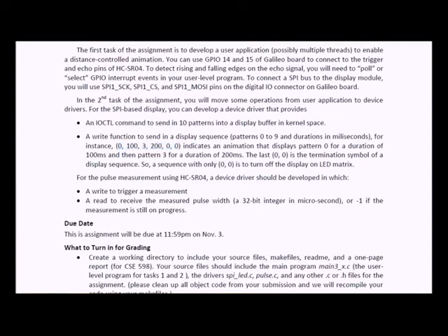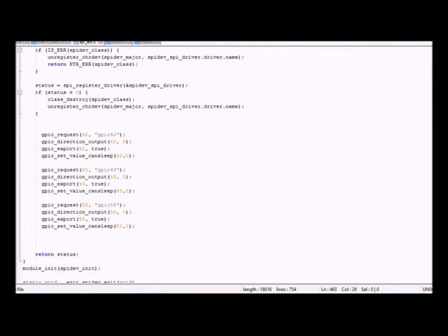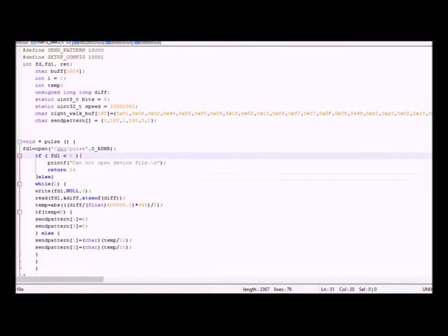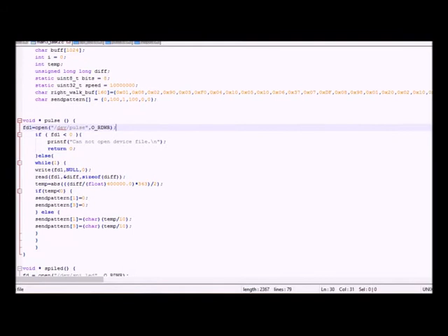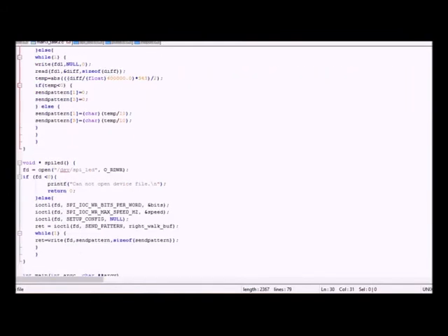Now let us look into the various drivers and the user application that we developed to use those drivers to work with the LED matrix as well as the ultrasonic sensor. If we look into the main task, here we use /dev/pulse, which is the ultrasonic sensor driver, as well as /dev/SPI_LED, which is the LED SPI driver that we developed to use the SPI LED matrix.